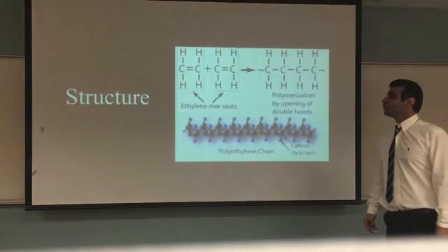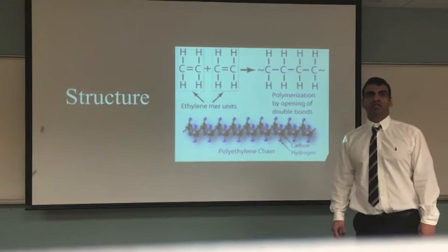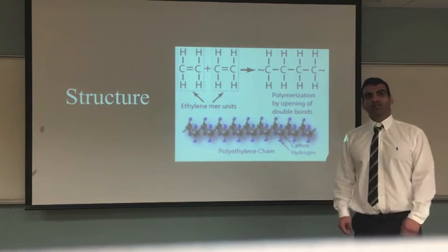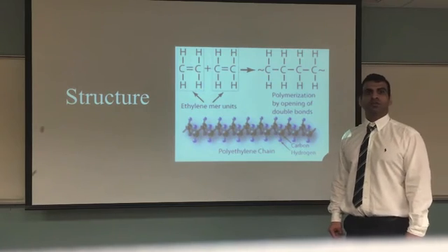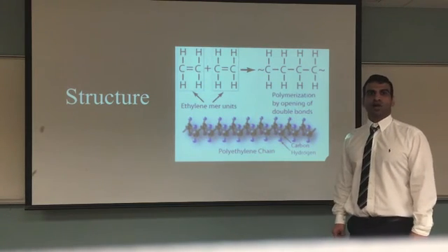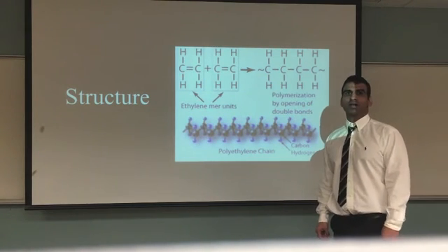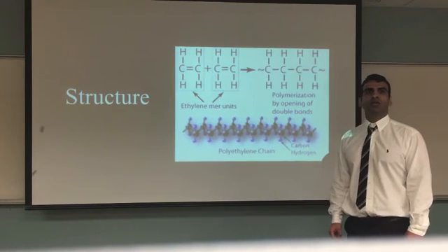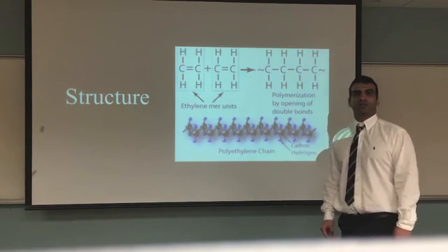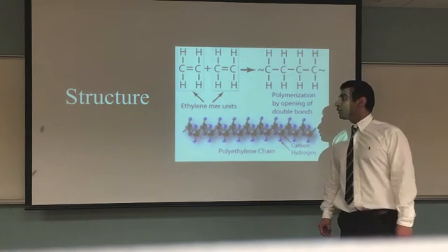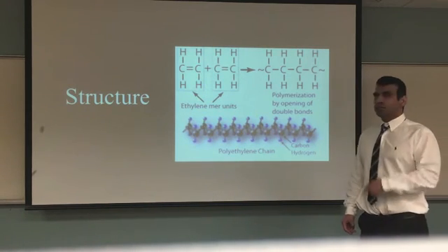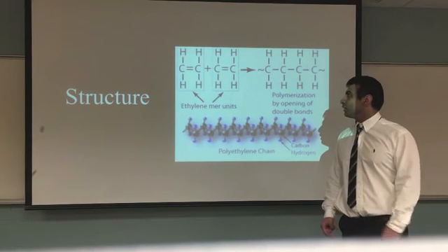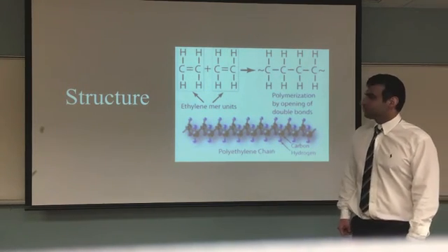Then we're going to talk about the structure of the polymers. In the cross-linked polymers, the units are linked with covalent bonds, which form a giant 3-dimensional structure, which is strong and tough, and the movement of the molecules is limited. The polymers with the linear chain molecule are soluble and thermoplastic, whereas the 3-dimensional polymers are not soluble in the regular solvents.